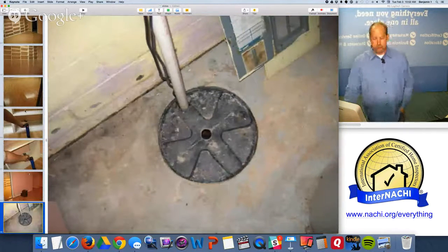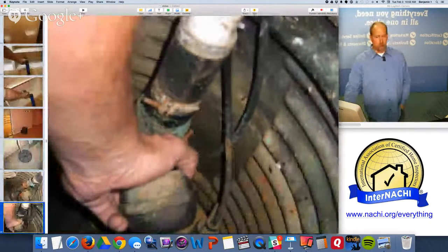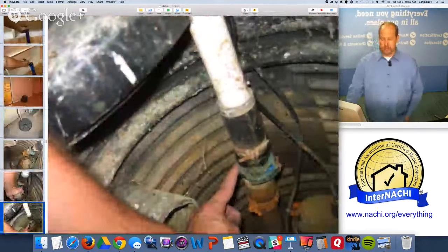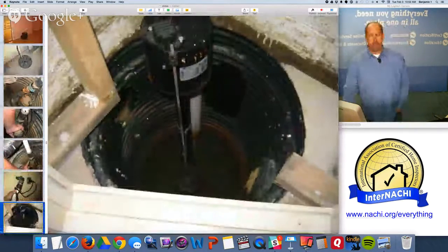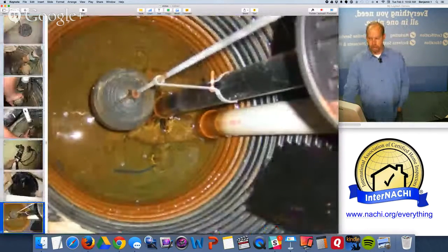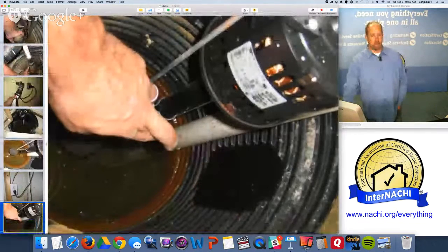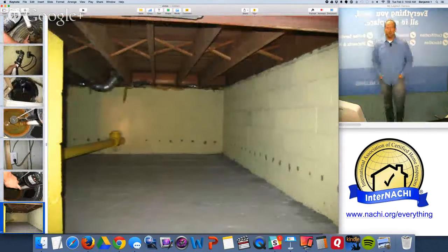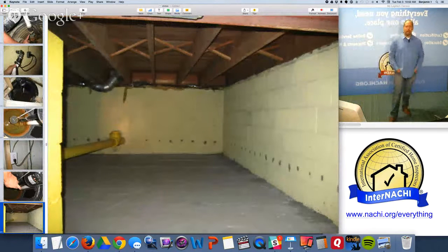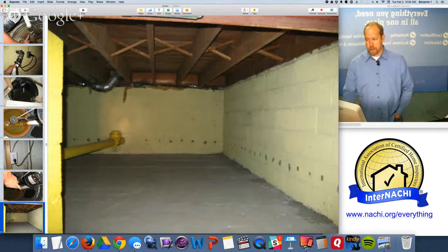And we have a couple sump pumps, one next to the electrical panel. It's dry, but it's very old, and it won't turn on. I lifted the float manually, and it didn't turn on, and there's no check valve. There's another sump pump that was installed. A lot of water in it, but it didn't work either. So it's not discharging. So you've got some water problems. Remember all the water problems on the outside? And there's water intrusion, moisture intrusion on the inside now. And there's indications of mold.